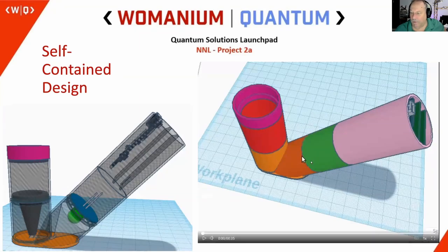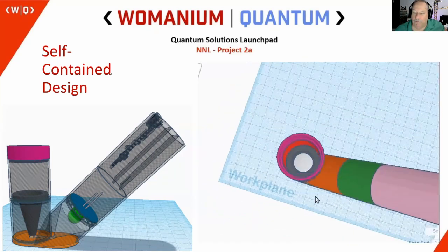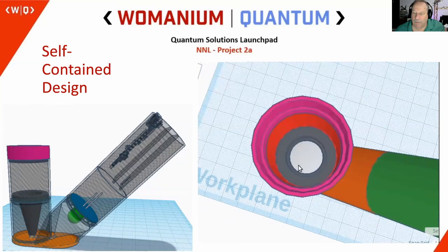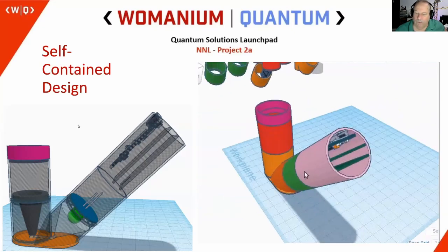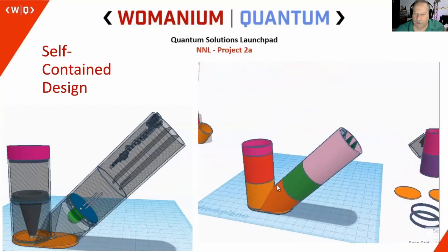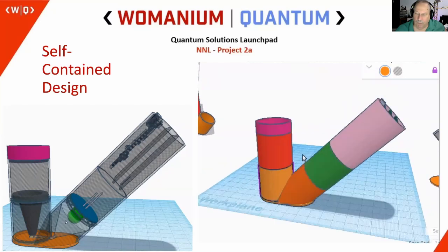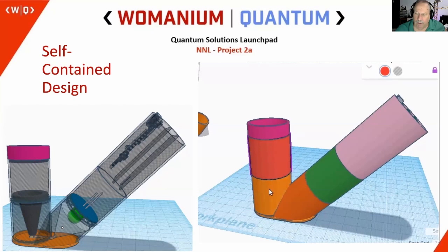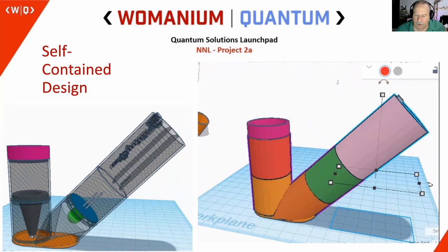This is one of the designs that we came up with. This is fairly self-contained. You can imagine this is about the size of a D-cell flashlight. What's going on here is we have a compartment where the control and electronics would live. In this particular rendering, we have a green LED as the green light source. We're funneling the light through a conduit here, like a light pipe. In the final design, we eliminated the light pipe and moved the LED right down to the crystal element itself.